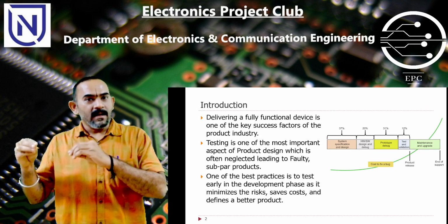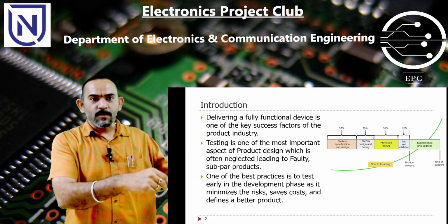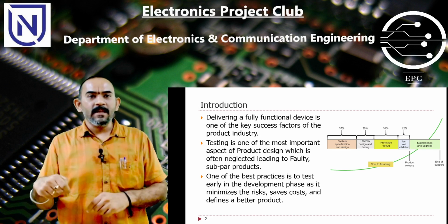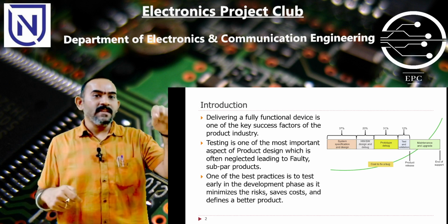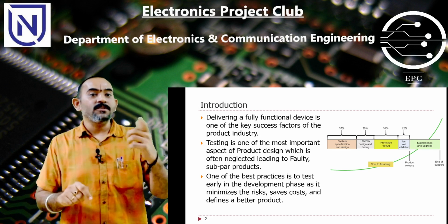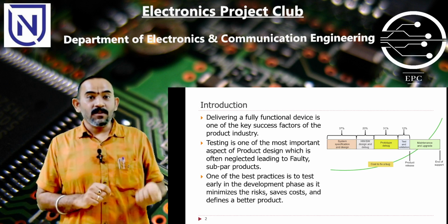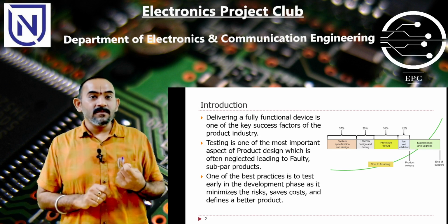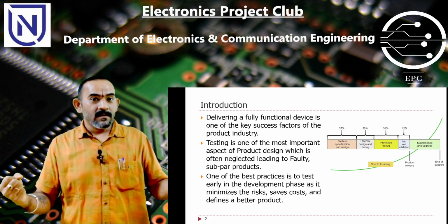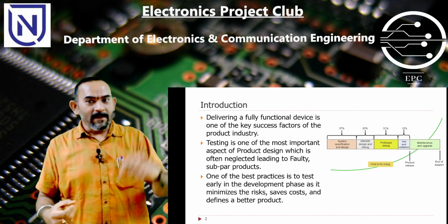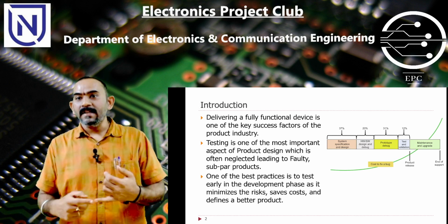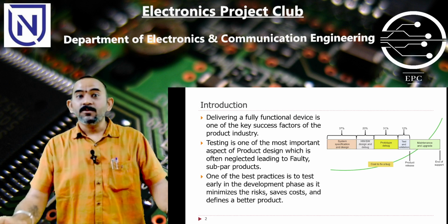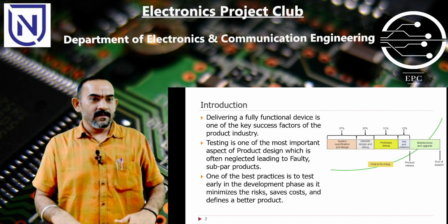And then when you are now giving the inputs, you don't get the outputs as expected. Now you see what could be the problem, and you find that one of the NAND gates inside the IC was not working. Now to correct this fault, what all things you have to do? Remove all the wires, then remove the IC, replace it with a new IC. Look at the time spent. You have to remove all the wires, and maybe that may be hundreds of wires, so you have to now reconnect all those wires.